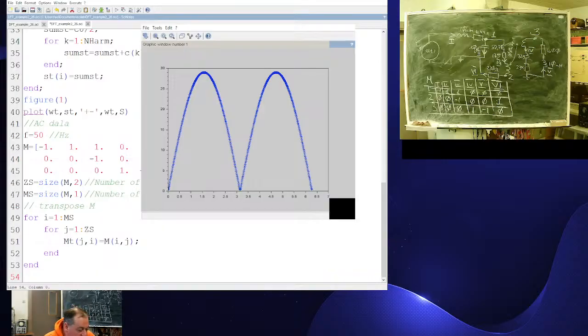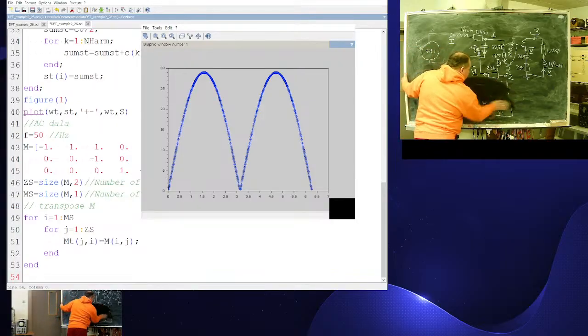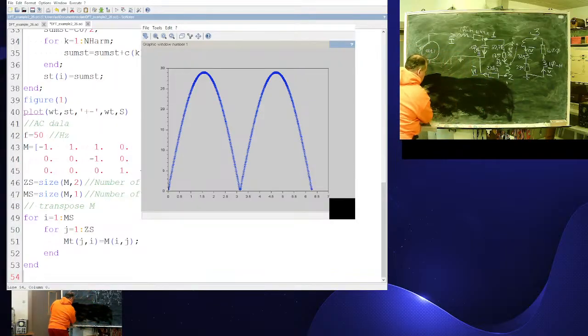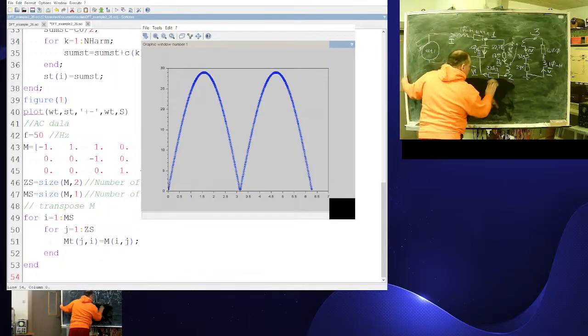What is my schematic missing? I don't have resistance. I have topology, connections, branch nodes, but I don't have any resistance. This should be done with the help of the resistance matrix. Resistance matrix forms in a special way. Its diagonal elements are complex resistances of branches.